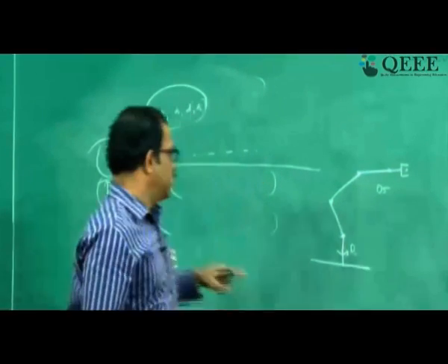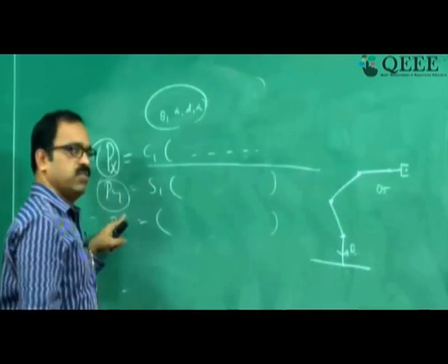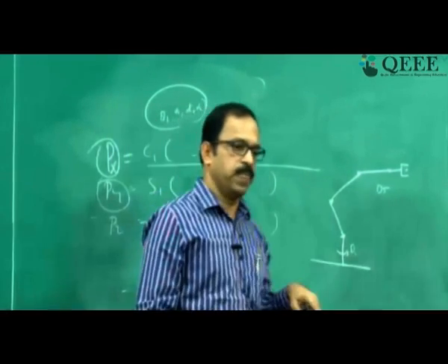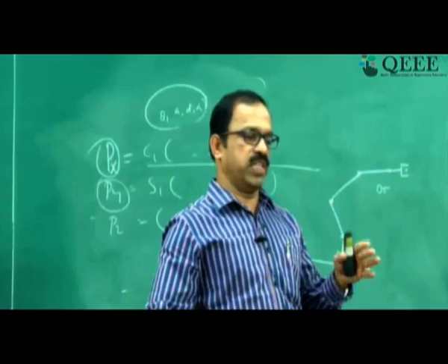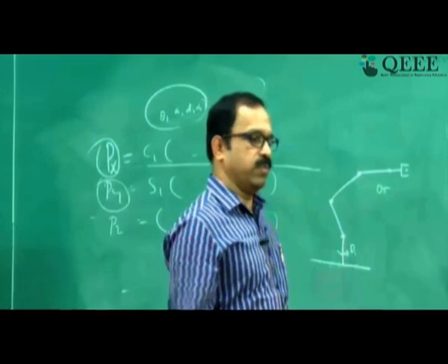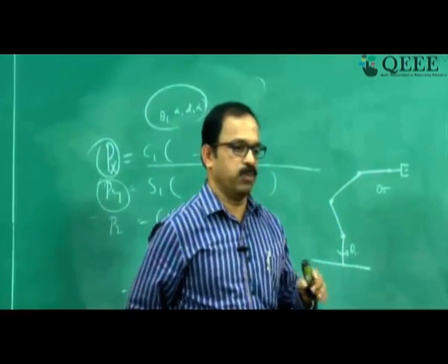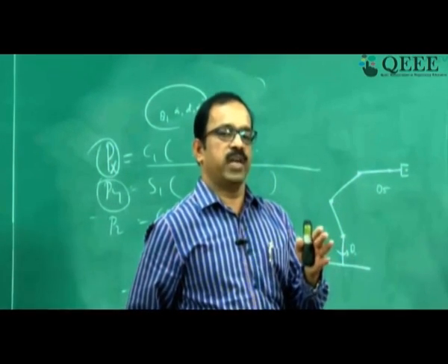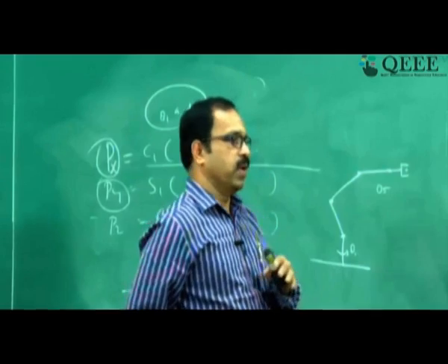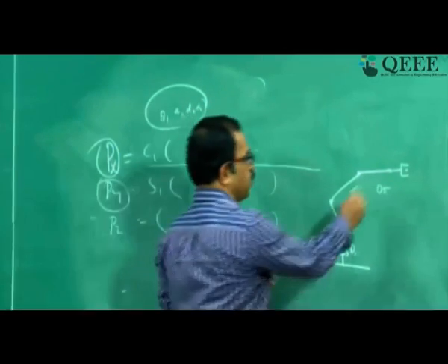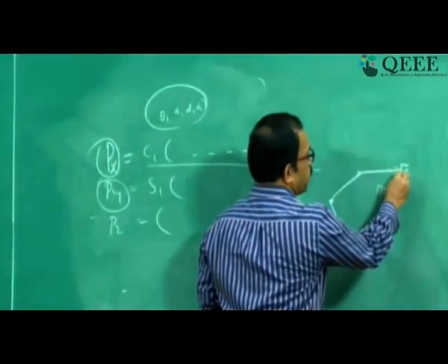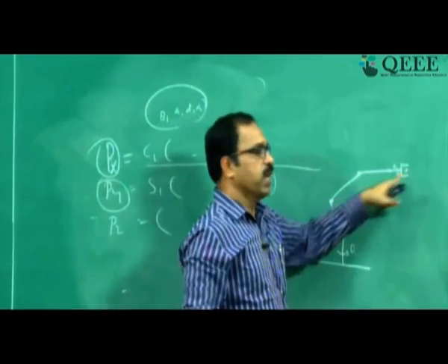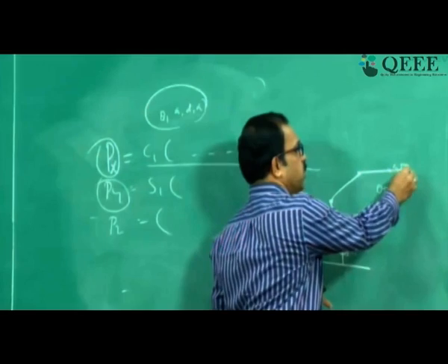Again, you can see that Px, Py, Pz is not a function of theta 5. If you look at the relationship, it says Px is equal to cos theta 1 multiplied by 177.8 C2 plus 177.8 C23 minus 129.5 sin theta 2 plus 3 plus 4. The reason is that the position reached by this tool, whatever the roll angle may be, is not going to change, and therefore the position is independent of theta 5.